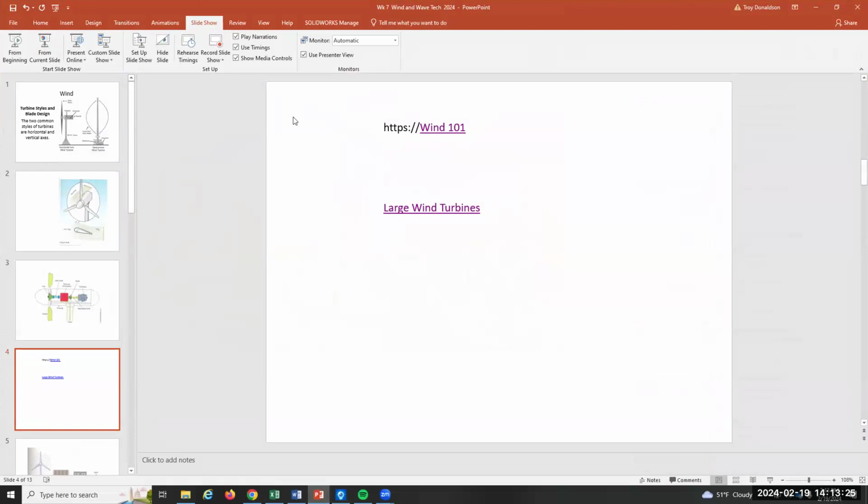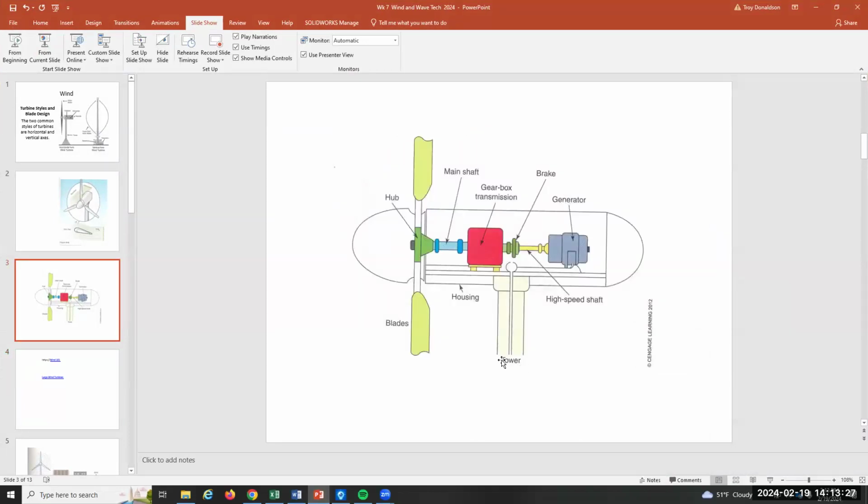Massive. Are the axes fixed? Like, it can only face one direction, right? Yeah, that's correct. But the whole nacelle, this whole thing is called the nacelle, right? This whole thing can rotate, right? Follows the wind. Oh, so they do. Oh, yeah, for sure. And does the wind cause that, or do they have some mechanism inside them? They have a mechanism that's tracking wind direction, trying to keep them on point. What's interesting is when you go on a farm, you'll see several pointing different directions and spinning. So that's just the wind flow in that area. They're very sensitive to that.